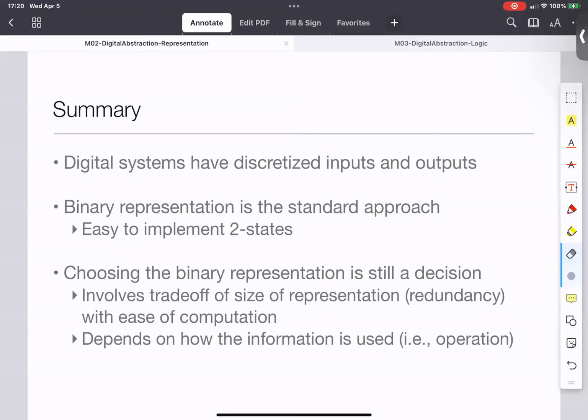Is that just something that you want to keep small as possible? And I was having a little bit of trouble sort of. Yeah, no, you actually want large noise margins, right? Because that would be more robust. The problem though is if your noise margins are large, then that means you are going to increase the span of the voltage, right? And if you increase the span of the voltage, that means your signals are swinging more. And unfortunately, power consumption depends upon how much the signals swing.